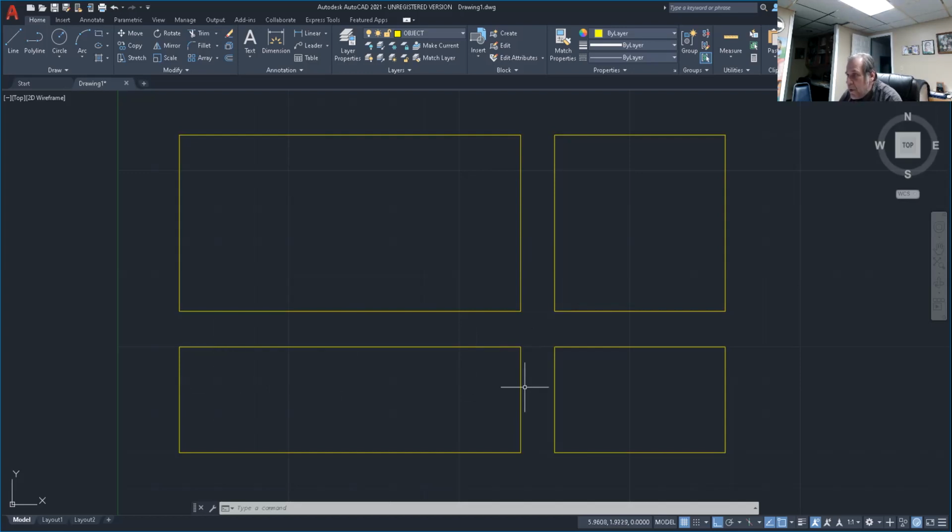We're going to draw it in the view that shows it true size and shape. When I say true size and shape, we can add all the dimensions to build it in one view. If you look at that, this notch comes over a 1/2 inch, down a 1/2 inch, over a 1/2 inch. So it's going to create that shape right there. Does that make sense? So I'm going to go back to my offset command. Remember I said offset was going to be one of your best friends in AutoCAD? It is, truly. So go to offset.